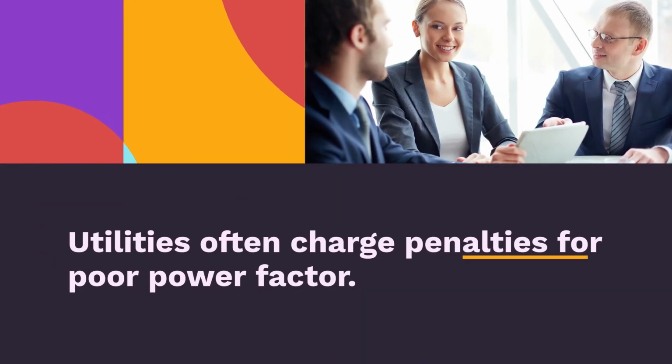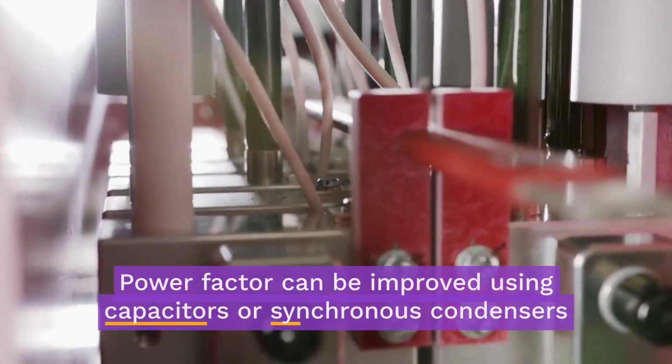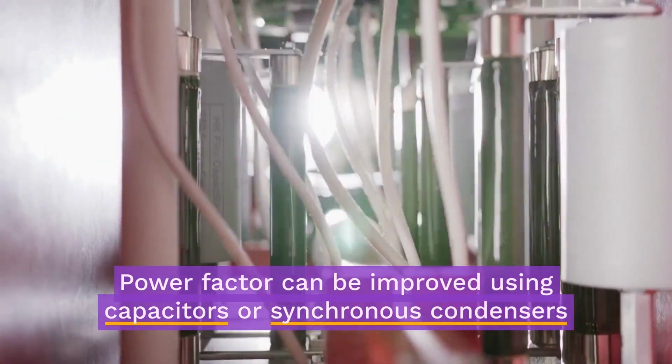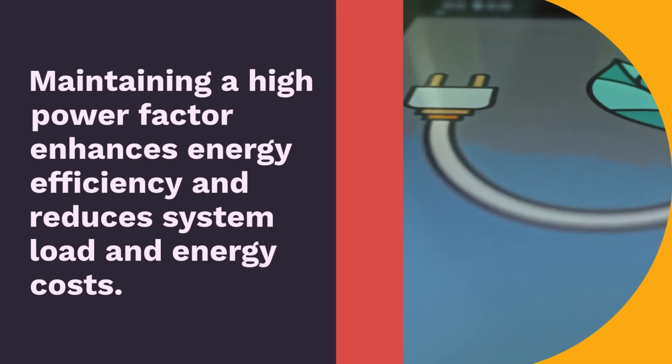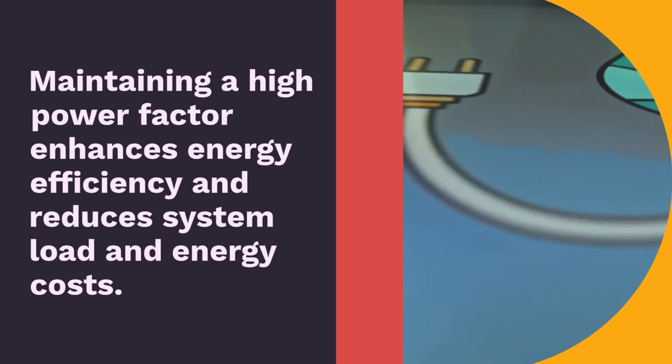Utilities often charge penalties for poor power factor. Power factor can be improved using capacitors or synchronous condensers. Maintaining a high power factor enhances energy efficiency and reduces system load and energy costs.